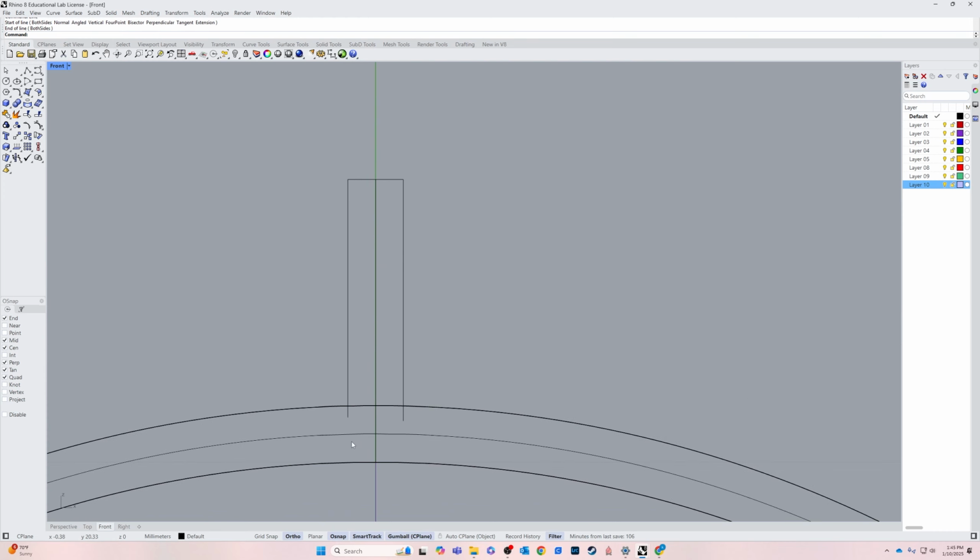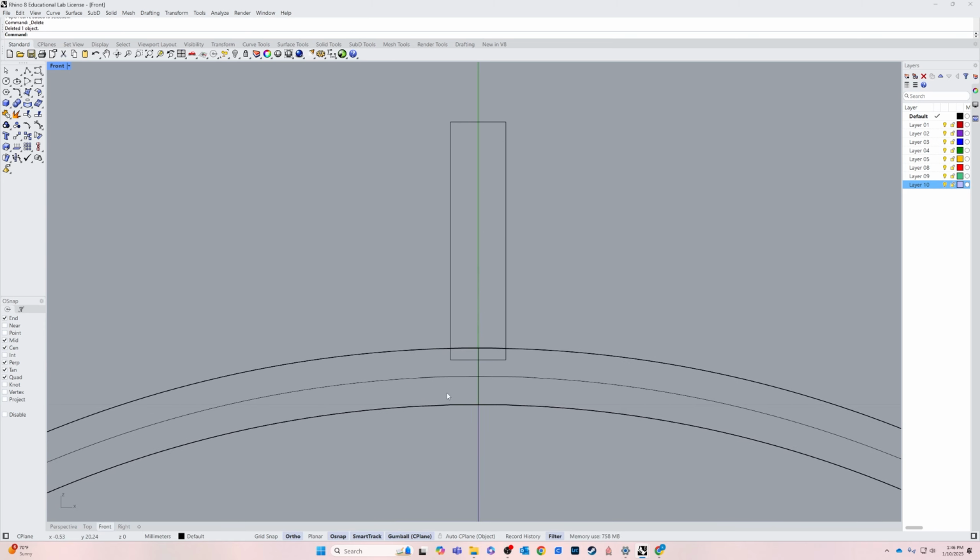All right. And I'm actually, I don't even need this line. I'm going to delete this line. I'm going to draw a rectangle from here to up there. And then I want to select, not this curve, that one, delete, click on this one, curve, delete, click on this one, curve, delete, click on this one, delete. Okay. So next I want to draw a line straight this direction, 4 millimeters, click, this direction, 4 millimeters, click. And then I'm going to draw a line straight down this way and draw a line straight down this way. Okay.